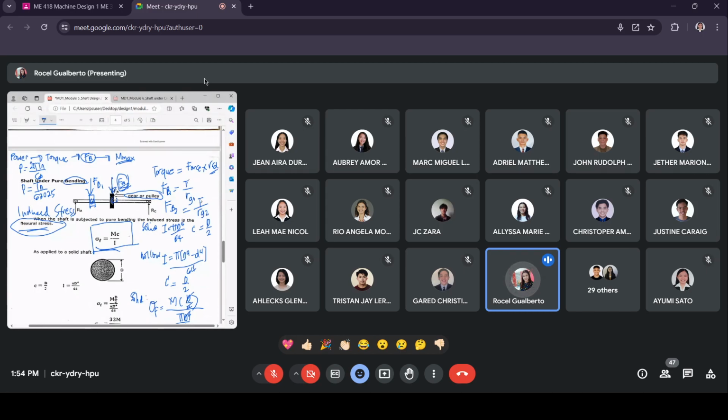For the value of the torque, that will simply be equal. Why is it equal? Because the two are mounted on a single shaft. That is why the torque would be equal. So the bending load varies only because of the radius of the gear. Nothing else.